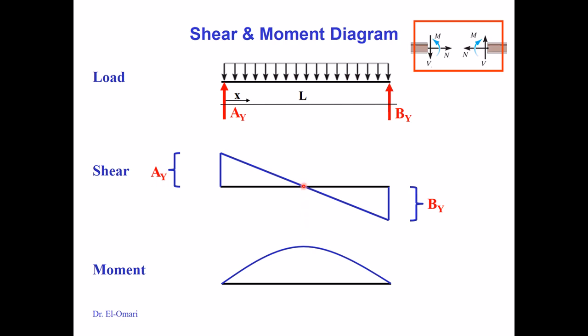So you have a zero shear, which means you will also have a zero slope. So the slope at this point is zero. The other important note is that because this is linear, then you will get a parabolic, or second degree, curve. Another important notes, and I summarize these in the table that you will see shortly.